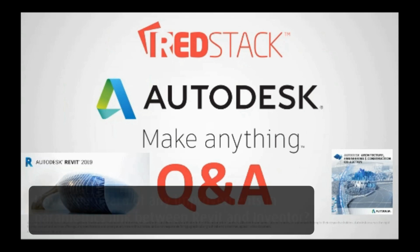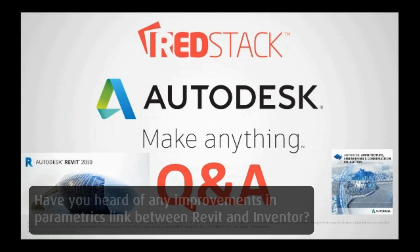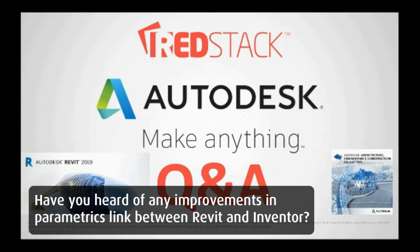Have you heard of any improvement in parametric link between Revit and Inventor? Gavin, absolutely nothing. The only way you could do it is through Dynamo right now. If you go to YouTube and Google Dynamo for Inventor, you're going to see a guy there, Franz. He created a plugin for Dynamo for Revit, for Inventor, and you could literally change something in Revit and it will update in Inventor.